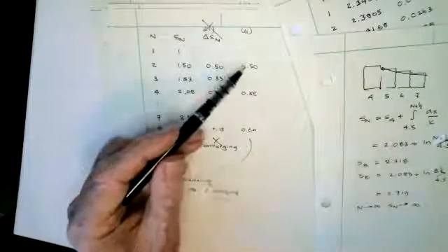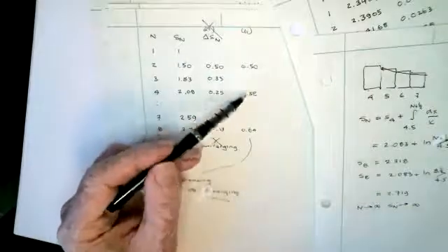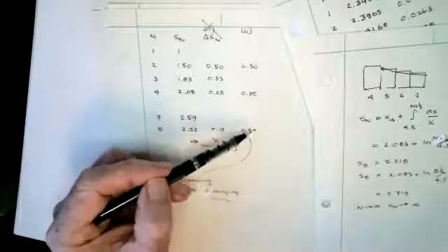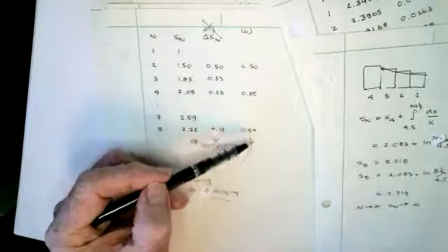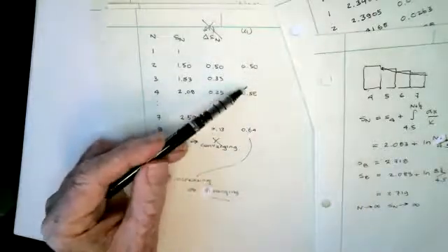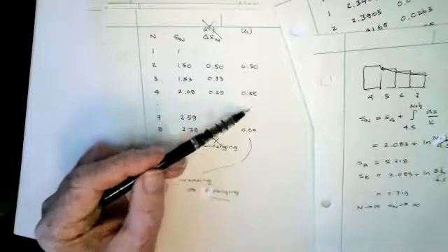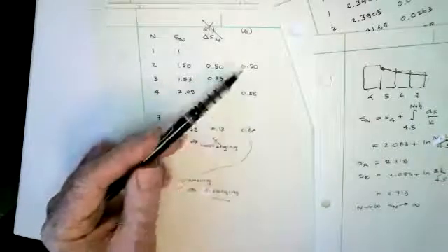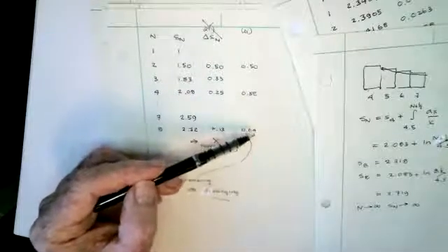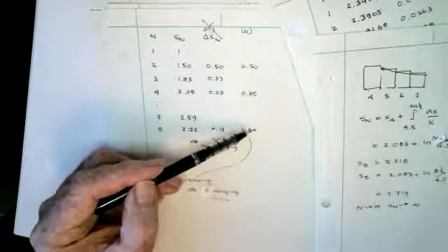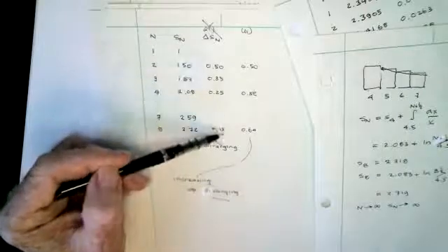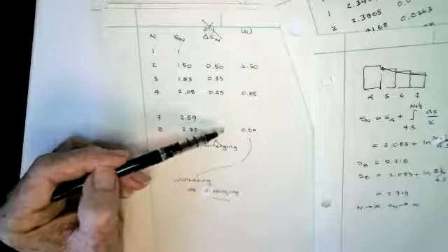And so this convergence check was saying, look, it's decreasing, so at least you wouldn't conclude it's converging. You could even decide these are consistent with diverging. I think the series is diverging without having this estimate. And we'll talk a little bit about that with stresses when this starts to happen. Sometimes it turns around and goes back down. Sometimes it doesn't. When it keeps on increasing with this check, that means you've got a stress singularity and you're trying to compute infinity, and you want to stop doing that. This sort of convergence check, though, would tell you everything's fine. It would start telling you that you've got an answer there, which you don't have.